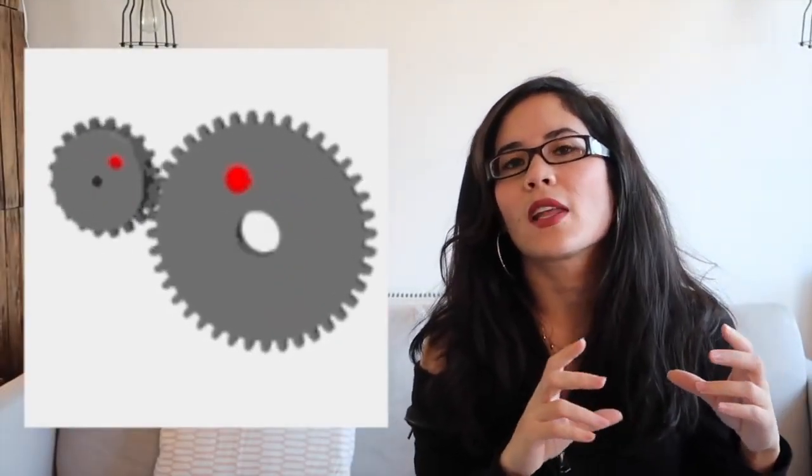If we take the opposite argument, and this time we start with a large cog and we make it attached to a small cog, then clearly as the large cog turns, it's going to cause the small cog to turn pretty much an entire revolution. So that will be spinning the small cog nice and quickly, so we've generated high speed, but we won't have generated a lot of power, and therefore the turning effect will be low.